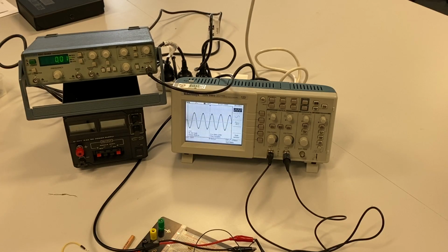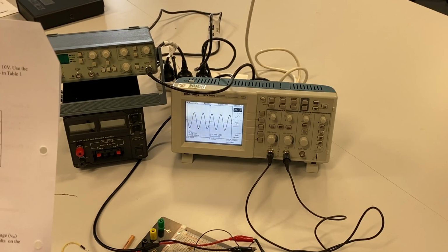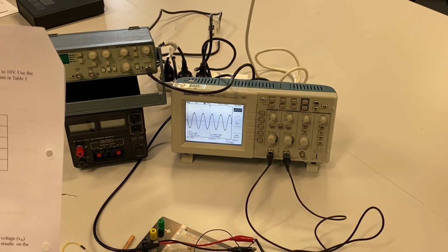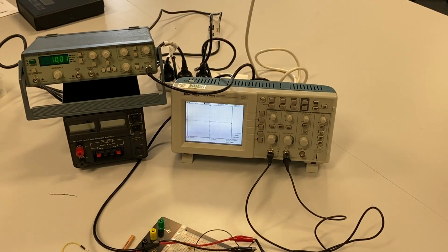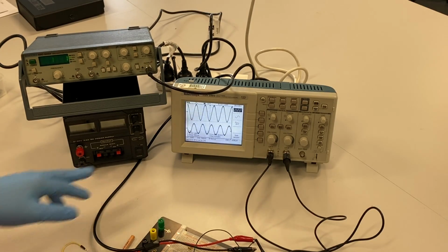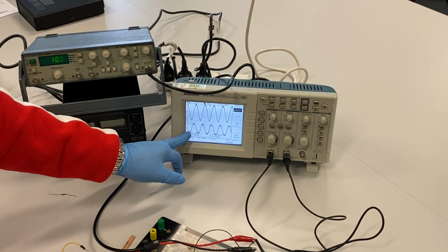connecting my circuit. What I'll do is, once you finish that and you want VL across the inductor and Vin, you want both of them to display, you just auto set, auto run. That's like our run. So what we see here are two signals. The input signal is channel number 1. The output signal is channel number 2, right?